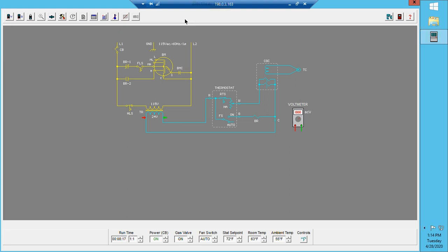If a load is good, I'm going to get a resistance reading because it's a load. I'm doing something with the electrical energy. If I get a 0, it means it's shorted. If I read OL, open load, it means that it's open, which means somewhere in the winding itself, a wire has broken apart.